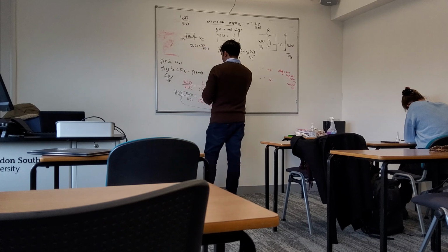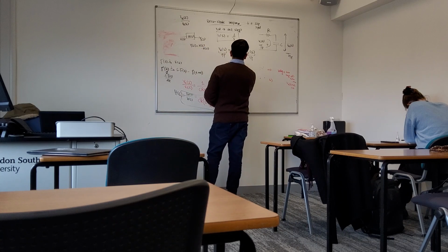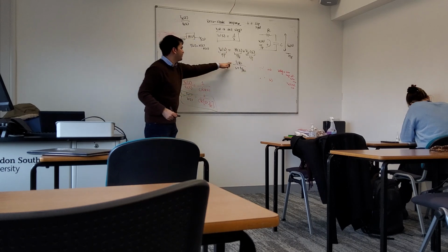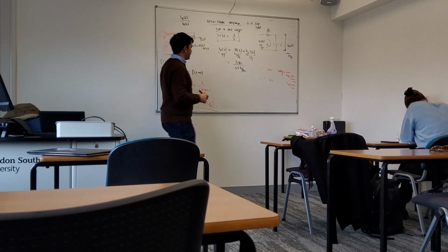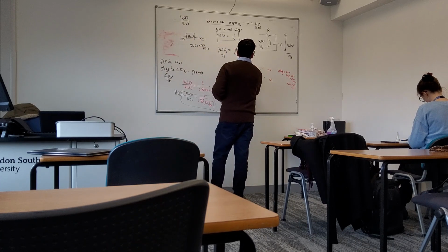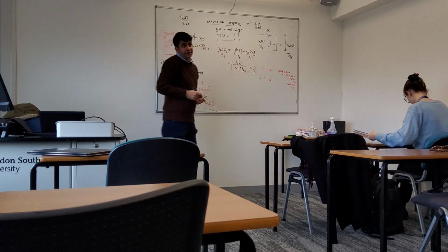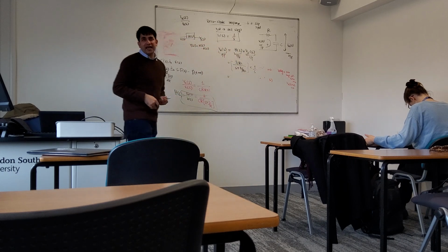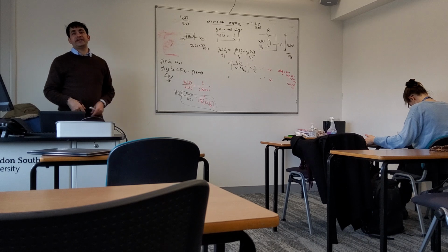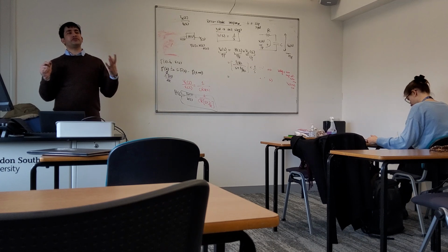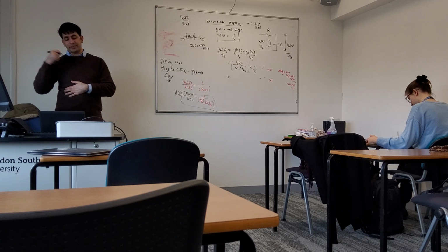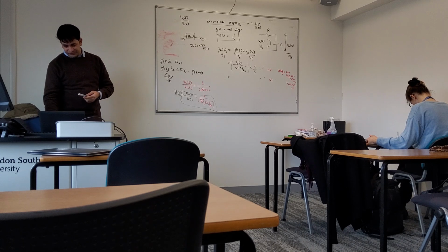So H of s here is written in this form. I can take CR, it's the same thing, but it's the known form of that. Okay. And I need to apply it with input. Input in this case was 1 by s, right? So now I have to solve it. And we know how to solve it. We know that we need to split it. Whenever you are asked to find response, you're always talking about time domain, but you're just taking help from Laplace domain and finding the time domain functions.